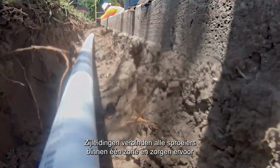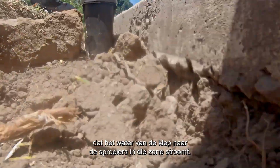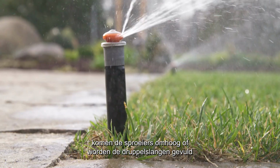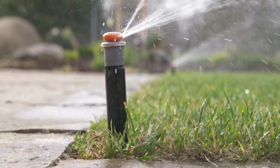Lateral lines connect all the sprinklers on one zone and allow the water to flow from the valve to the sprinklers in the zone. When the valve opens, the lateral line fills up with water and the sprinklers pop up, or the drip lines are filled with water and build pressure to activate the emitters.